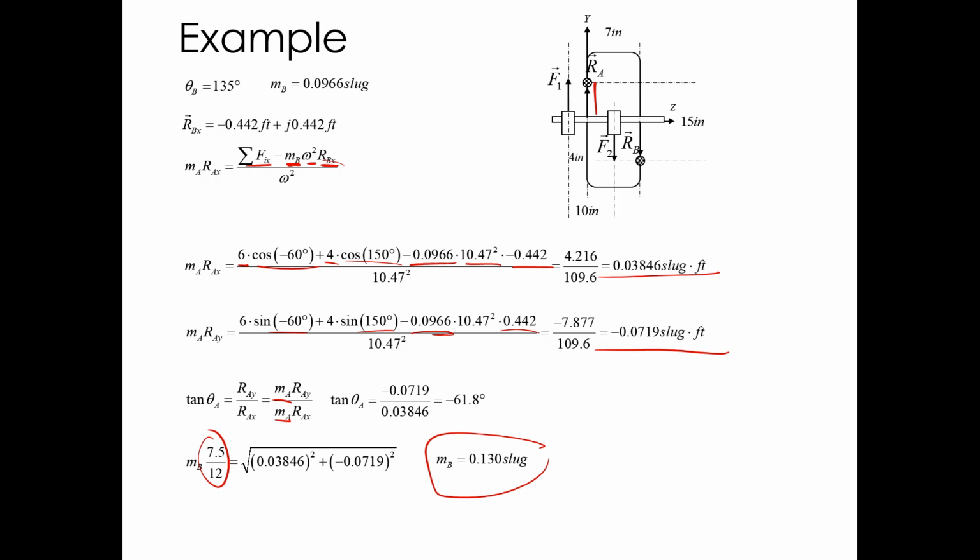a tire balancing rig. The only things you'd have to watch if you're going to actually build this rig and do it, you'd have to make sure your force transducers would measure the force on the bearing. You need to equal and opposite it to get the force on the shaft for the way we've derived our equations. You could easily go back here and just put a minus sign in front of all of the forces and directly use the forces that your bearing transducers would measure, but you're still going to have to be careful about that. You have to be careful about your units.